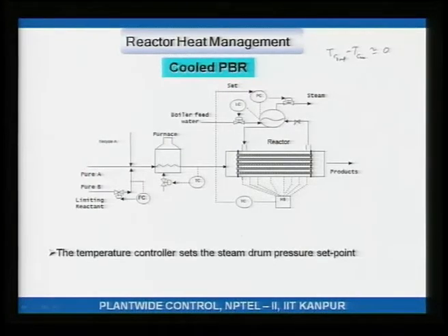Inside the reactor, you have got, for example, a temperature profile that looks like this. There is a hot spot. This hot spot, like I said, moves with operating conditions, with changes in the feed conditions, with changes in the cooling circuit conditions, and so on and so forth.